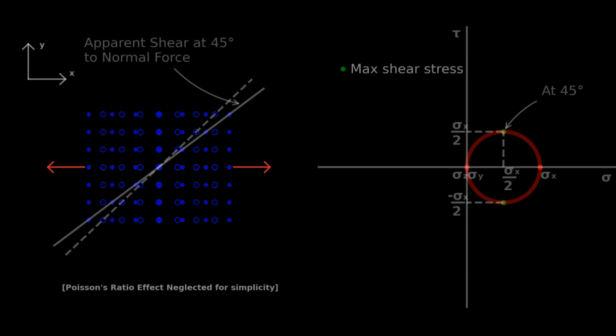Now, why did I draw it at 45 degrees? Because I know that the maximum shear stress, a 90-degree rotation from the principal stresses in the Mohr circle, corresponds to a 45-degree rotation on the element. So this will show it most clearly. But if the line was drawn at 30 degrees, it would still exhibit this rotation, just to a lesser extent.